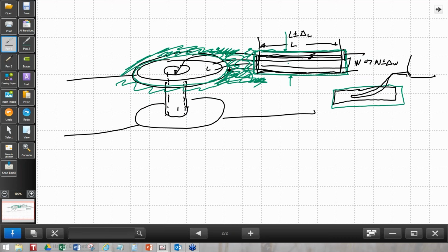So in general, you need to look at the manufacturing tolerances for both the lead and the solder mask and the registration of them, and add an allowance on the outside to the size of the solder mask. The same thing you can do on a via, but if the via is not part of a pad, if it's just a via for connecting between layers, you can leave it open. You could even tent it. Tenting is where you close it all together, and it would be okay.